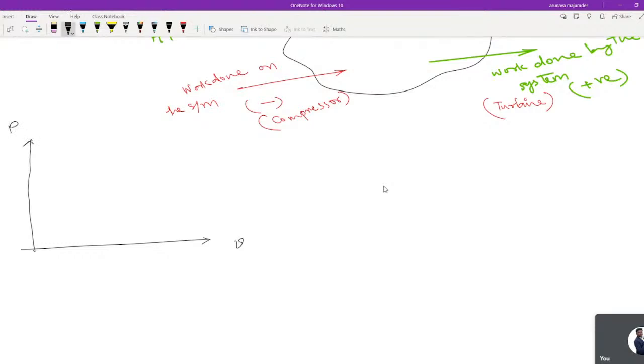So this is actually the general equation, work done 1 to 2. One more thing: work done 1 to 2 is not equal to W2 minus W1. What does that mean? When shifting from one state to another state, we cannot write the work done like this. That means the work in the process from 1 to 2 does not equal W2 minus W1. We cannot write this. Sometimes in GATE they also ask whether it is equal or not equal.